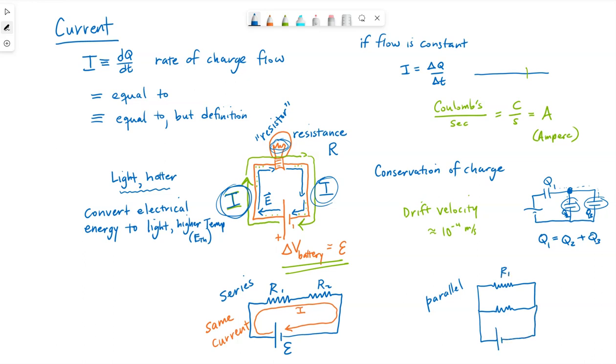So resistors in parallel mean if we follow a path around a circuit, then there's a choice. So parallel, we always have to have some sort of junction in here, where if we're following the path from one end of the battery, when we get to the junction, we can either choose to take our path through R2, which will get us back to the other side, or we could choose to go up through R1 and back down, which will get us to the other side.